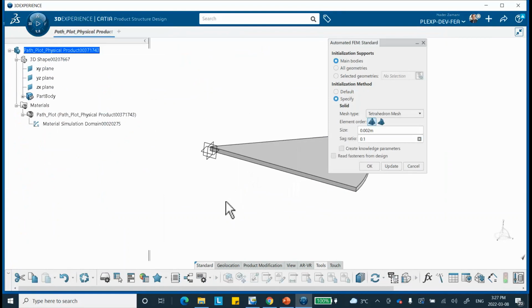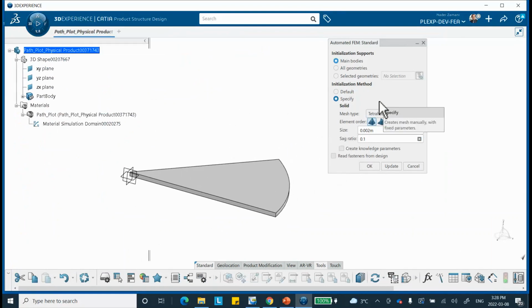Standard model, standard. Now I'm going to use a sweep mesh. I can use tetrahedral, but because this was a pad region, it's very amenable to sweep. So I'm going to make it sweep, so it's going to be hex elements throughout. As far as the size goes, I'll leave it like this. If necessary, I'm going to change it. I'm going to make 2 layers. Basically, this is half of the thickness of the disk, 2 layers of elements through it.